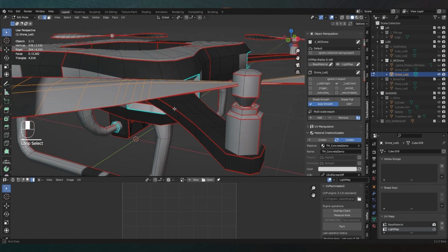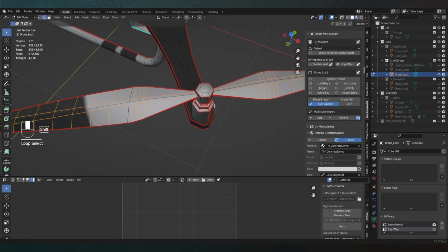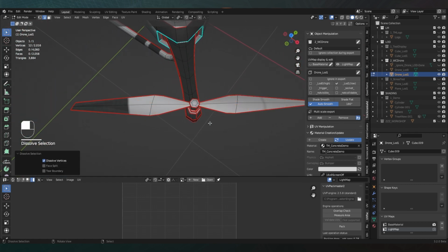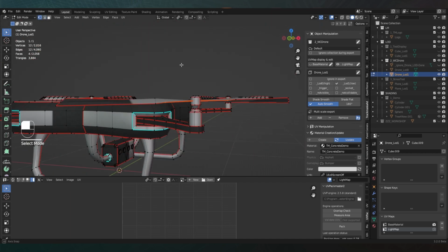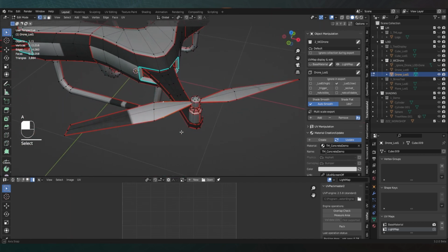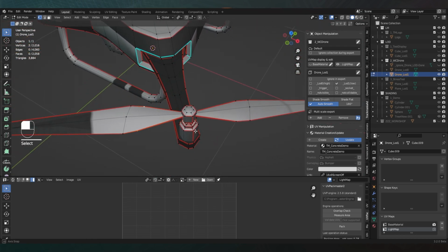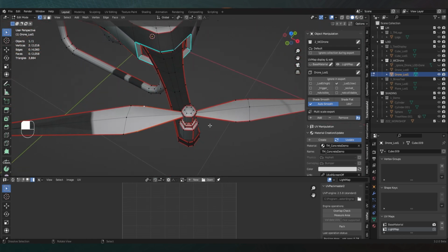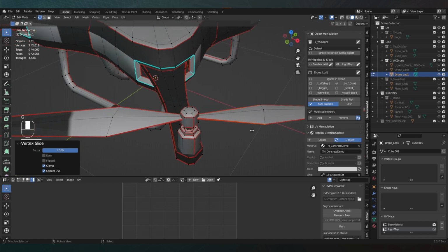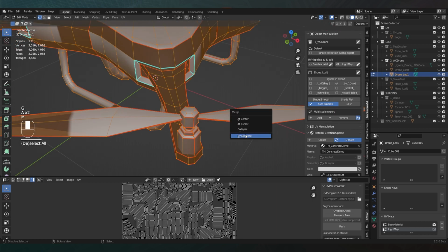And at this part, I think it was a bit tricky to keep the light map layout in place. If you have floating vertices like these, which are not really looking intended, then select them, hit double G, and you can slide them across the edge. This is something that helps a lot in 3D modeling, and in our case, it helps us simplify. So after doing that, make sure to remove doubled polygons.